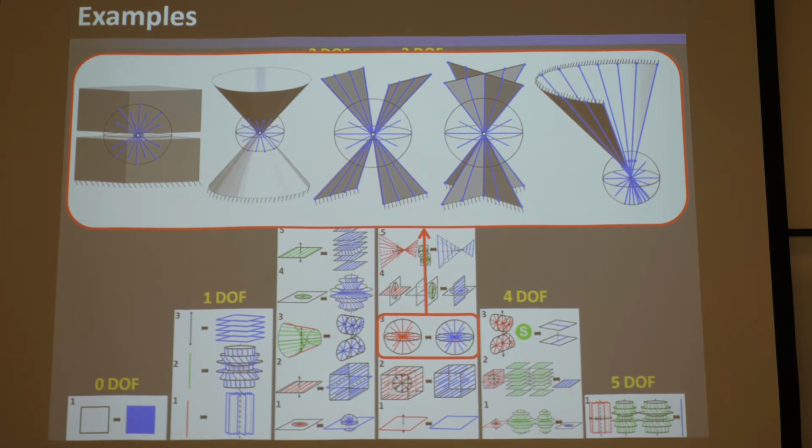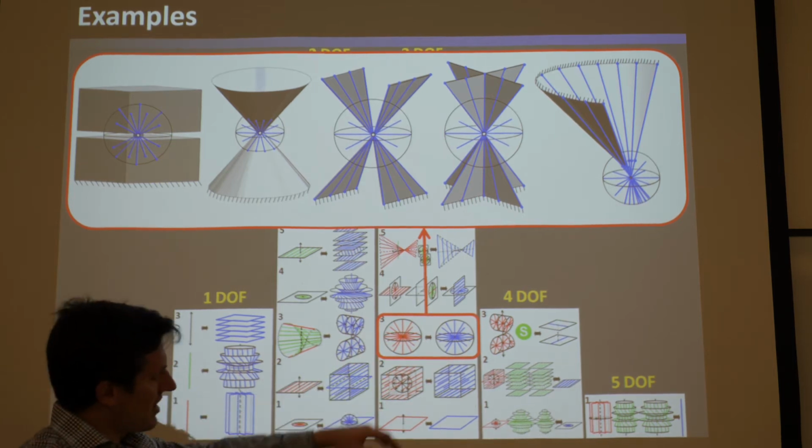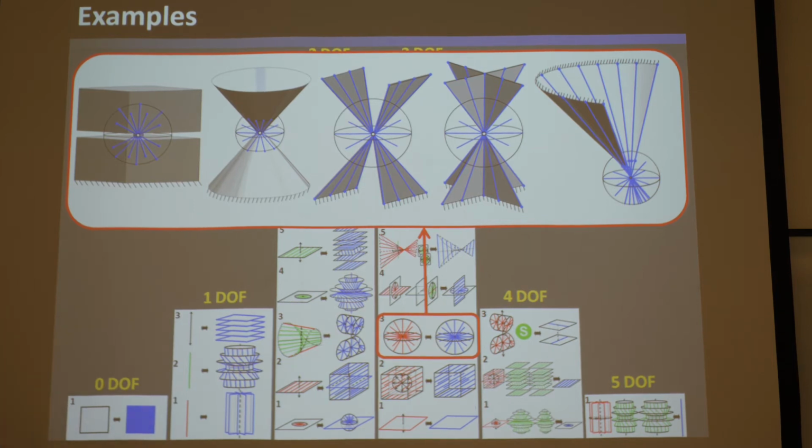Okay, that may not be terribly intuitive, but if you cut it up and you put giant blocks on both sides, and you did a modal analysis, you'd see the first three modes correspond with these three rotations. Okay. Okay, and sometimes these get a little messy, especially when you compare it with modal analysis. It may be that the fourth mode shape is associated with a natural frequency that's not so much larger than the three of its freedom space.